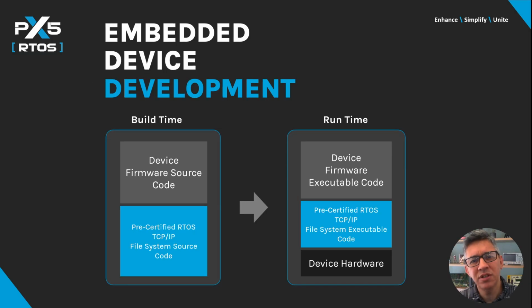The functional safety of a typical safety-critical device can be viewed from two different perspectives: the build time and the runtime. Let's start with build time, which is the phase during which all device firmware that's typically written in C and assembly is compiled, assembled, and linked into one image that will be flashed to the device. Once loaded, the device powers up, and then the device executes the firmware image. The execution is what is called the runtime.